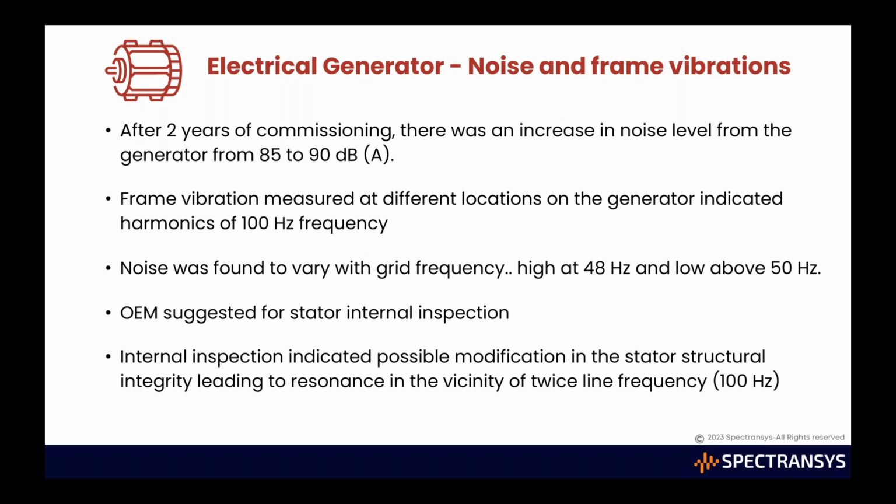Then this data was compiled and shared with the OEM, because the field engineers, nobody understood what was happening on the generator. As the vibration analyst, the data was collected and the problem was presented to the OEM. The OEM said they wanted to have some internal inspection of the generator stator and the winding. The internal inspection indicated a possible modification in the stator structural integrity, leading to resonance in the vicinity of twice the line frequency.